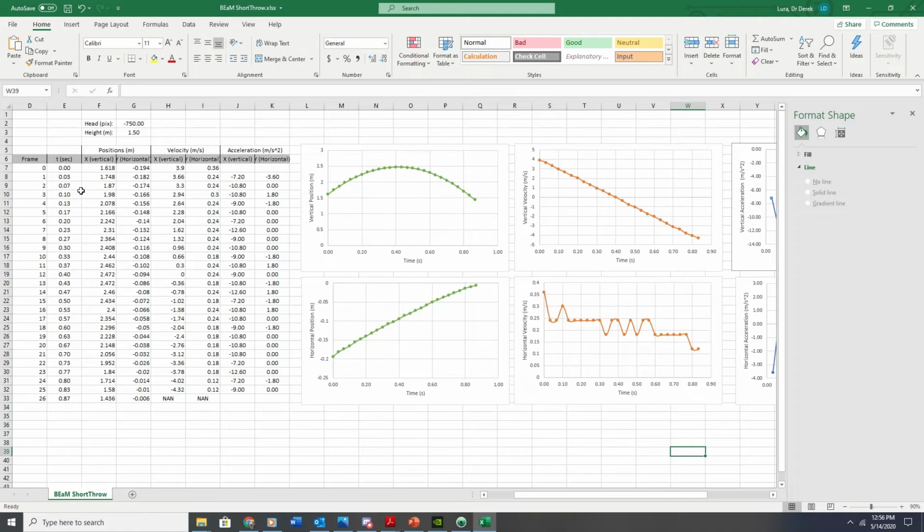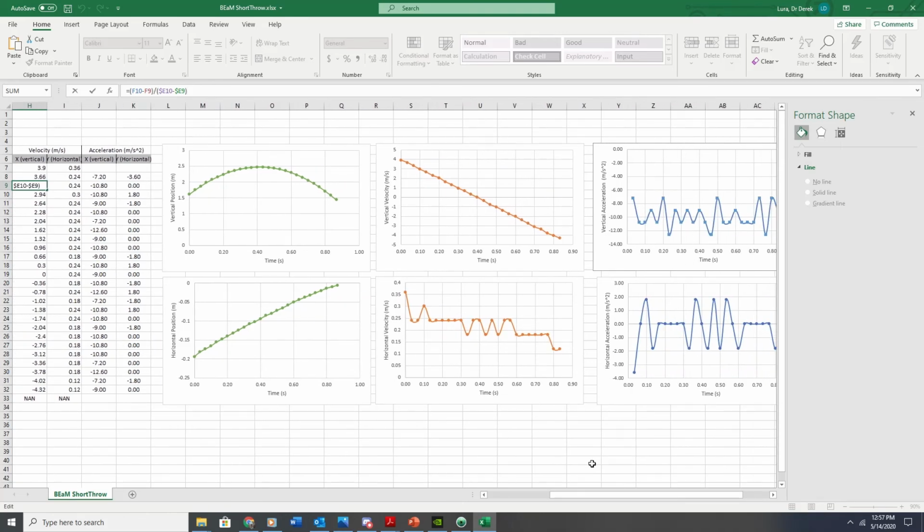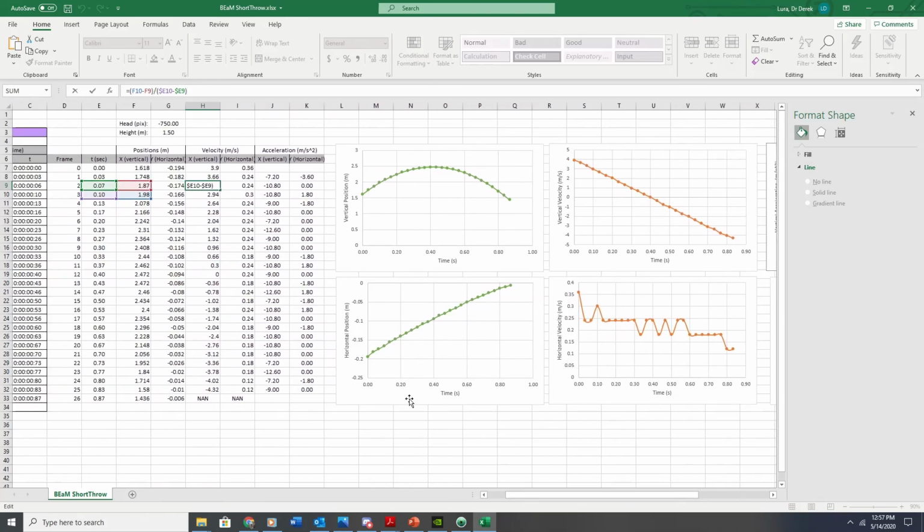So if I have a very high frequency recording and a little bit of shift, the delta t on that derivative, the denominator in my velocity and acceleration calculations, this t2 minus t1 or whatever it is, if that value is very small and there's a little bit of noise, you can get a very large jump, like you see in these charts here.